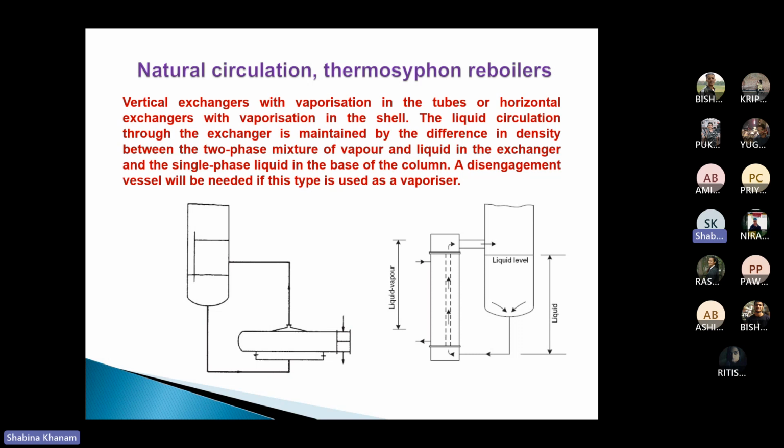When the fluid is in the shell side, it has to pass through less length in comparison to when it enters the tube side, because in the tube side it needs to follow the complete flow, and then enter the distillation column. So here we don't consider tube side vaporization or boiling when horizontal placement of exchangers is considered.